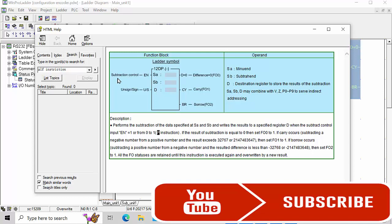See what it says: subtraction control, this is the enabling point, and the outputs are D equals 0, difference 0, FO 0. SA means the minuend, SB means the subtrahend, the value which you would like to subtract from this value. You have to write it here. D is the destination register to store the result of the subtraction.